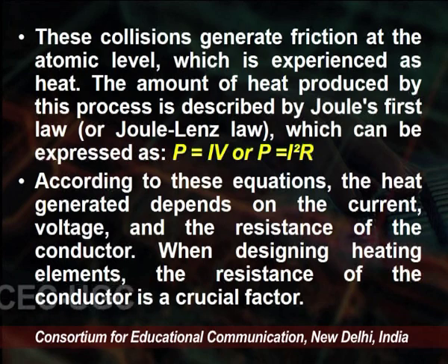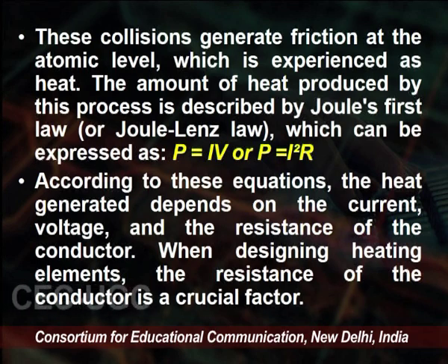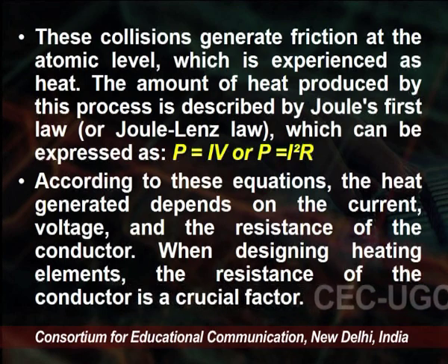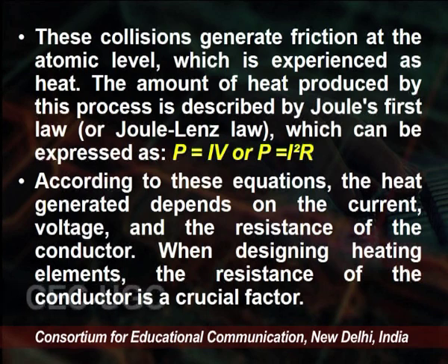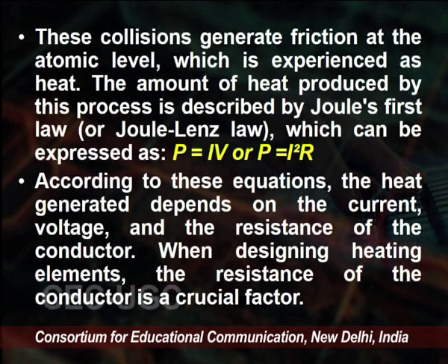According to these equations, as P is equal to IV, the heat generated depends upon the current as well as on the voltage. As P is equal to I square R, it also depends upon the resistance of the conductor. So when designing a heating element, the resistance of the conductor is a crucial factor, and keeping the resistance in mind, we prepare the heater accordingly.